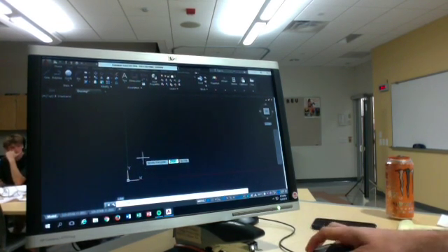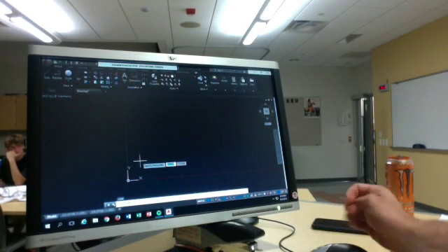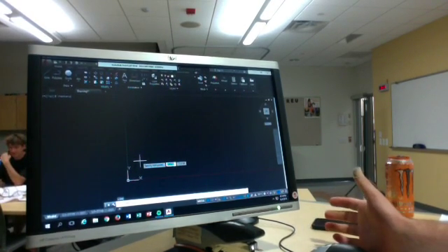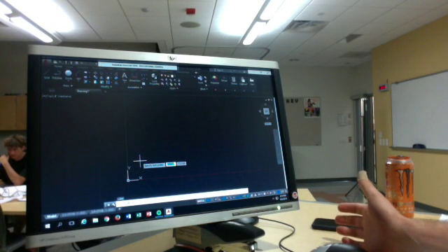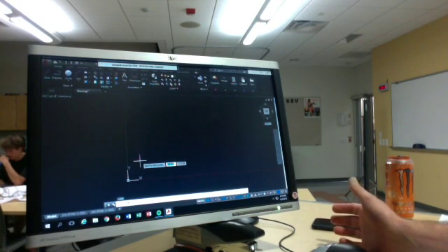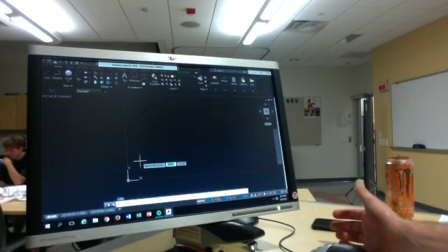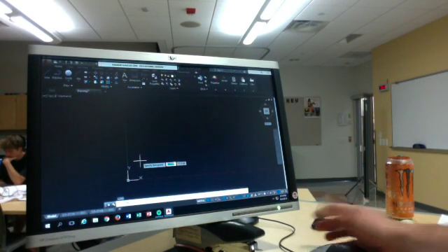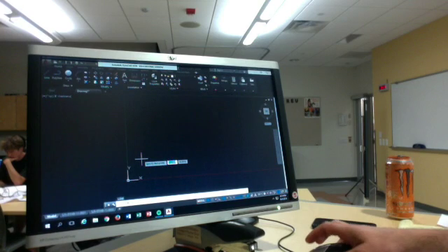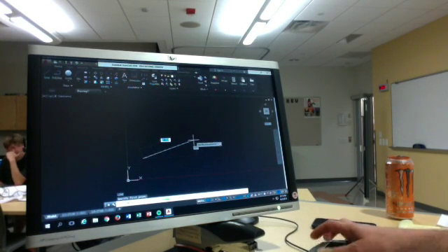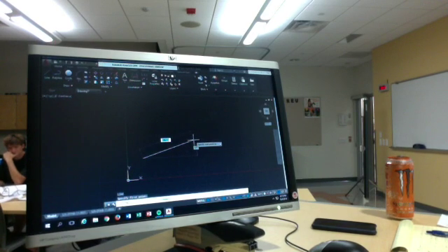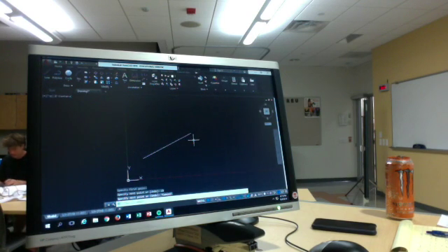So lines, it's literally just vectors. The difference between this and, let's say, Photoshop, is that Photoshop is an actual image. Vectors take up a lot more file space, which is why printers don't like printing from AutoCAD, but we force them to anyways. So, when drawing a line, like I was talking about earlier, you have the dynamic input. You can make it 54 units long, you hit tab, and you make it 25 from your horizontal.